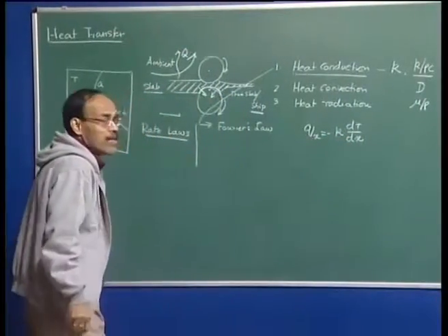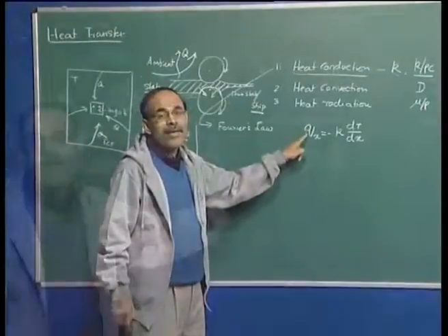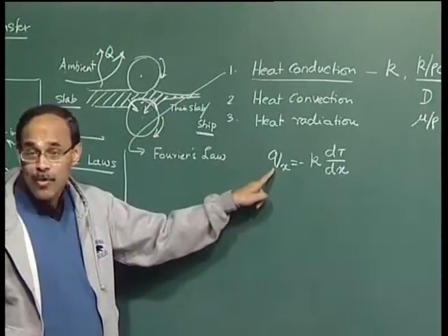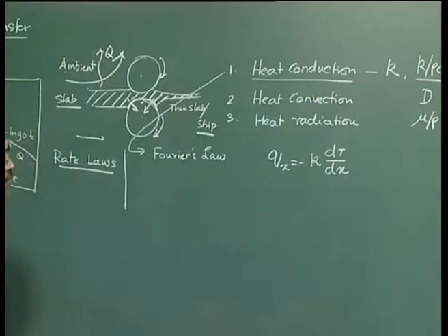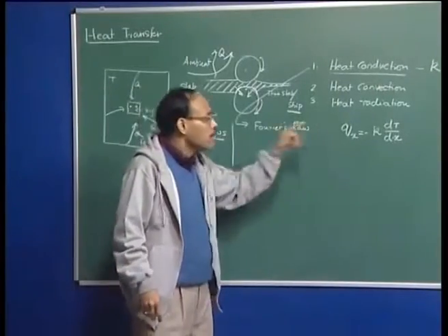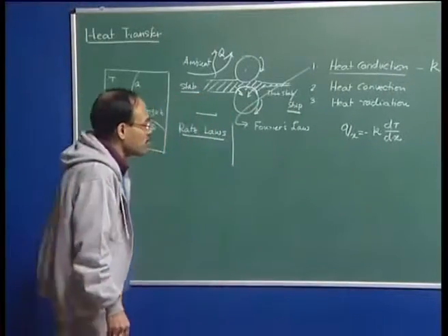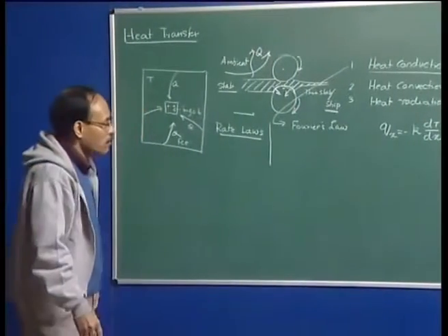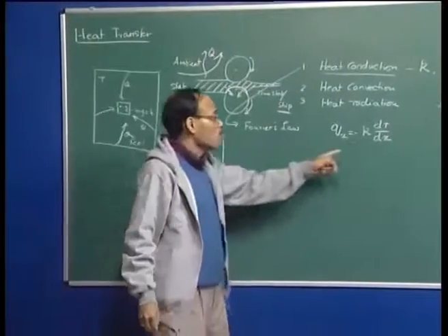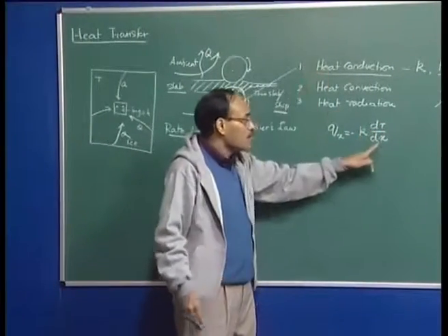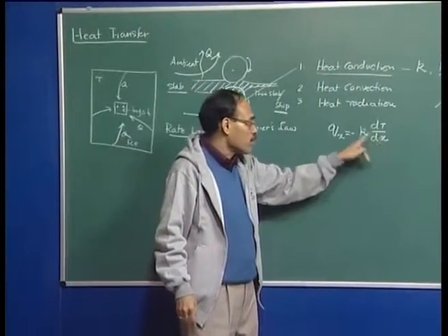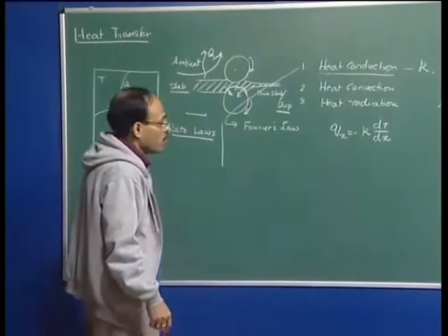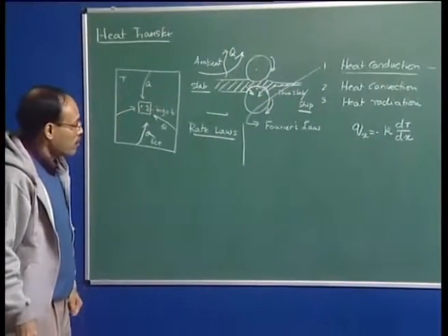We can similarly write the heat flux along the y direction. The definition of flux all of you must be knowing. It is the amount of energy, heat flux is the amount of energy per unit area per unit time, and the area is normal to the direction of heat flow. So, heat flows from a region of higher temperature to a region of lower temperature, and that is why it is preceded by convention with a negative sign.